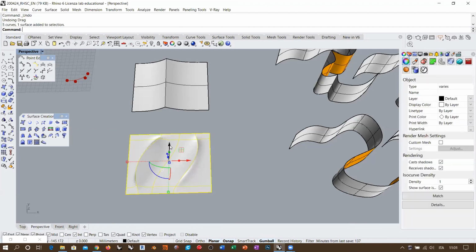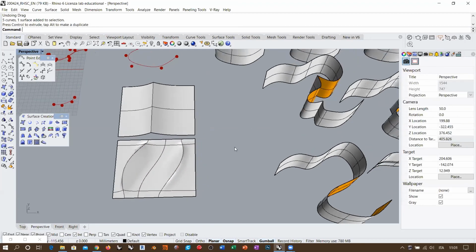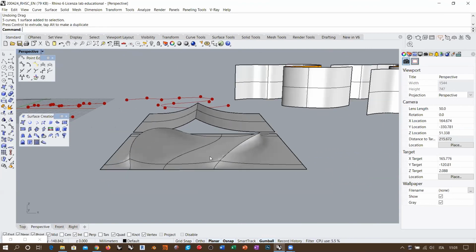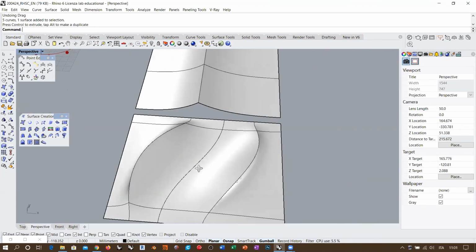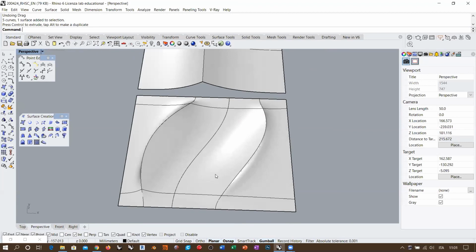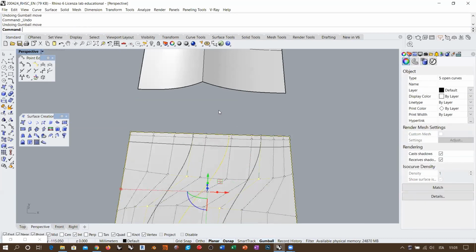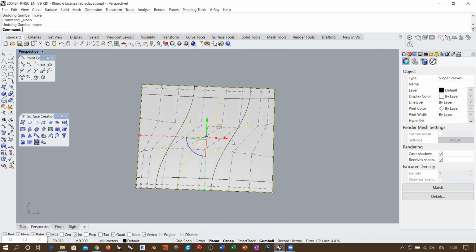Okay, and so also, yeah, tell me. Basically, these two knot lines that you generate make the last part smoother because they create four control points in the last part. Is it correct? You mean this knot line, yes, here? Yes. Okay. Look, actually, I need this not for smoothness control, but to determine when the crease is going to disappear towards the edges.